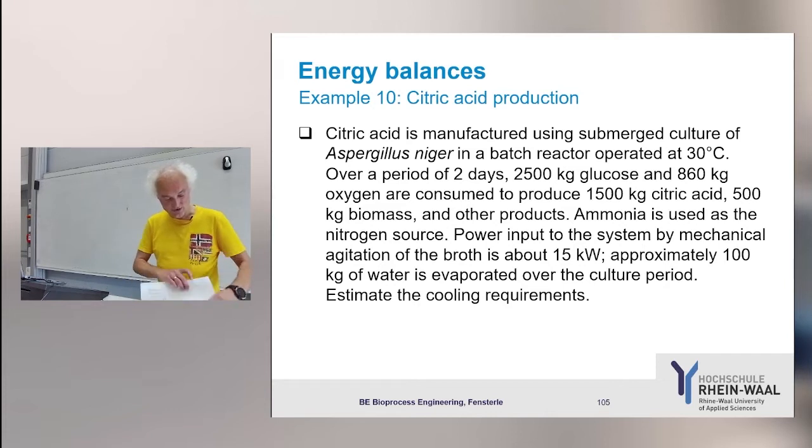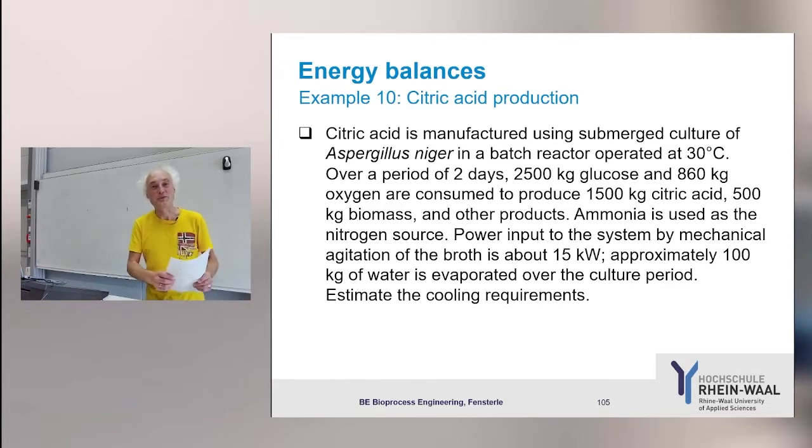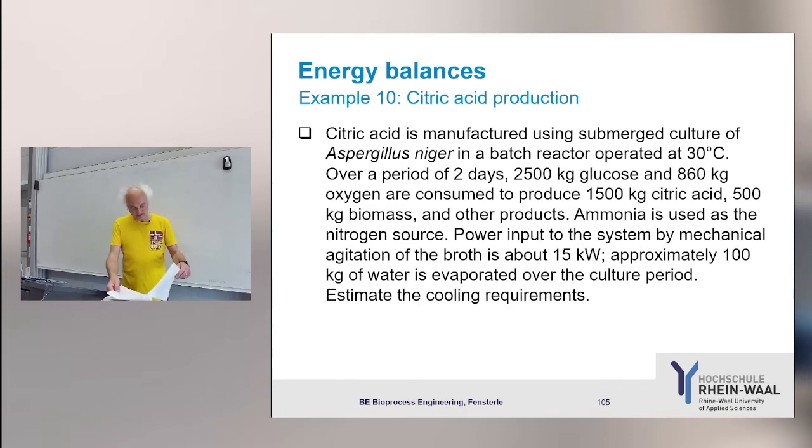As I told you, I do the same. I always carry my formulary with me, night and day, wherever I am, I have my bioprocess engineering formulary with me. And then I go to energy balances, and in contrast to you, I have not marked the equations, and then I see that it is minus the heat amount of oxygen consumed. Here we are. Delta H of reaction for fully aerobic metabolism is minus 460 kilojoule per mole.